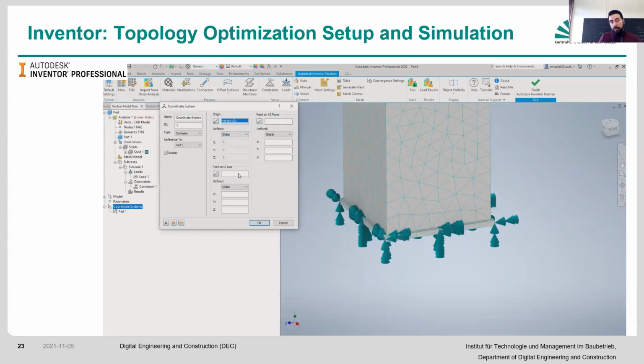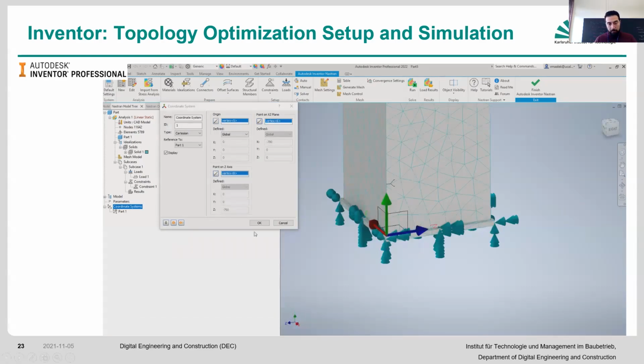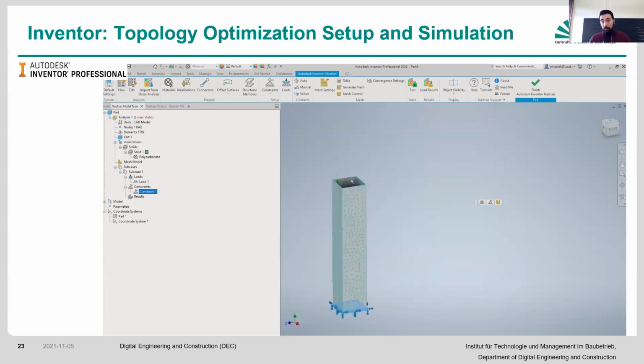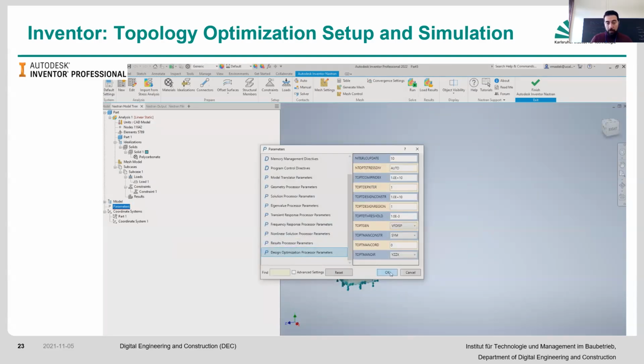The last part that you have to take into consideration is the reference coordinate system that you have to provide. Here, you need to provide, let's say, a point on the origin, a point on the XZ, and a point on the Z. So here I'm just going to basically follow suit and do what you have here in terms of the XYZ. However, you can change that as well, and then have it with respect to that. And in that case, you have to make sure that your parameters, let's say, the symmetry that you're asking with respect to 2 or 3 or more planes that you've defined, if you want those symmetries, then you have to go and check it and ensure that those symmetries are proper. Okay.